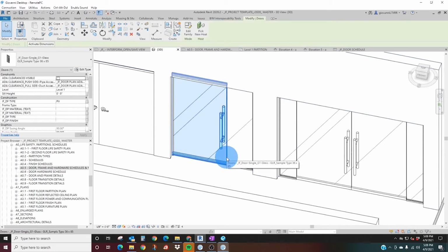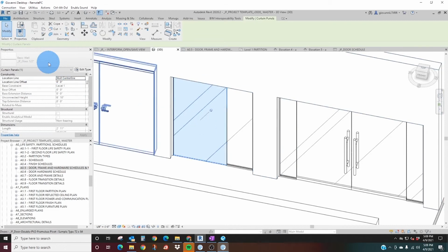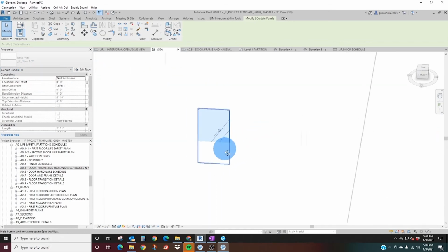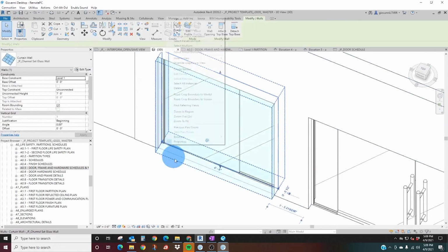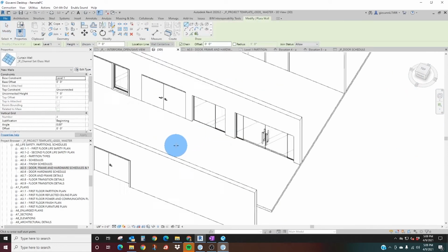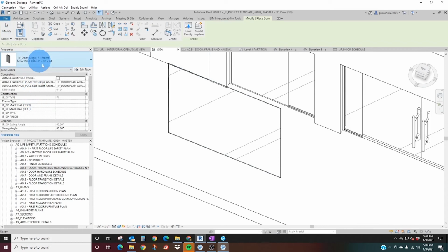we will insert. So if I delete this door, and I'm just dealing with our curtain wall. If I click our panel, you can see we use a standard wall type, and we represent our glass with a wall type so that they can host our door families. So this is actually a wall type, but it's titled IF half-inch glass and showing a glass panel here. So once I've created this curtain wall, and actually I can just do a duplicate of this just to show this example. I'm going to go ahead and create similar, and I'll just put it out here just to show this.